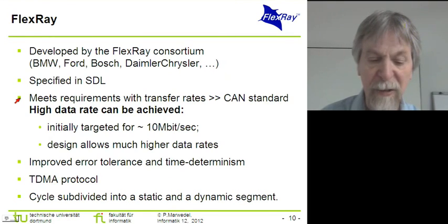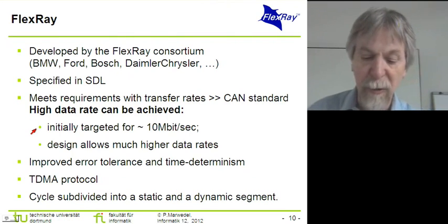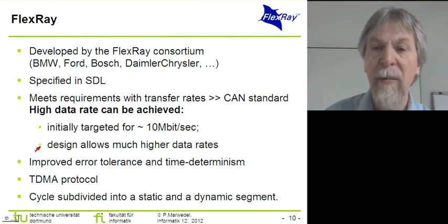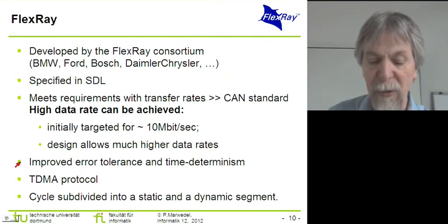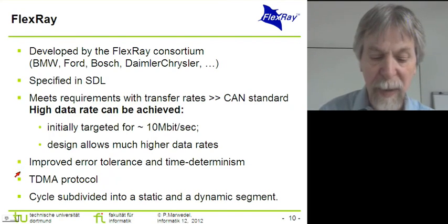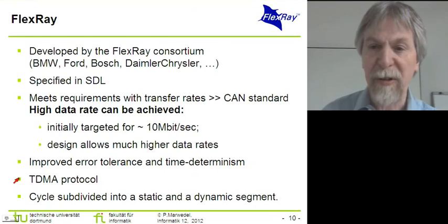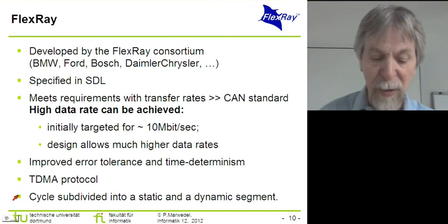With this FlexRay standard, we can meet higher transfer rates. Initially, FlexRay was targeted for 10 megabits per second, but the design allows for much higher data rates. Also, compared to the CAN standard, the FlexRay standard does provide a much more improved error tolerance and much more time deterministic behavior. And it is, as can be expected from my introduction, using the TDMA protocol.